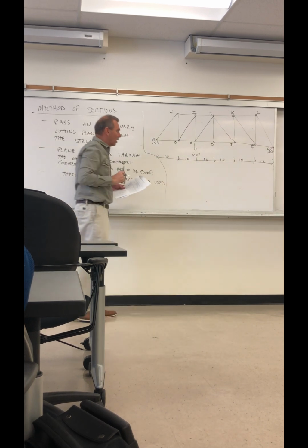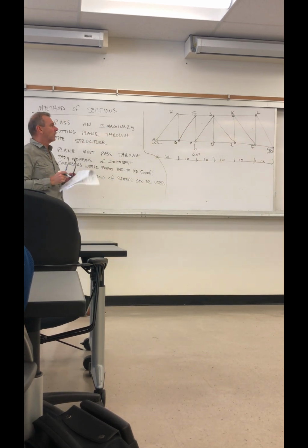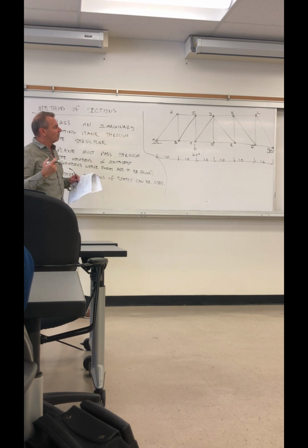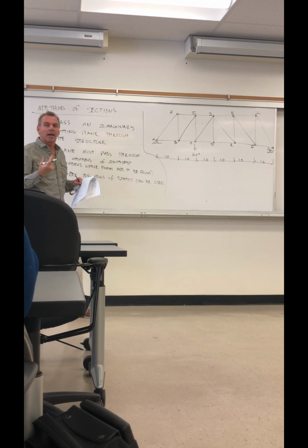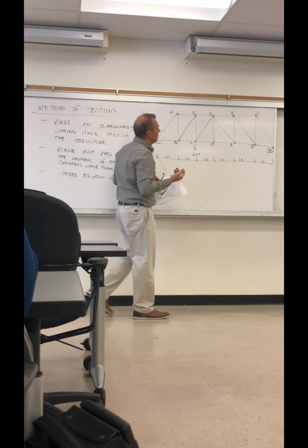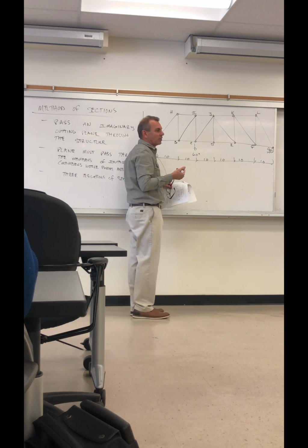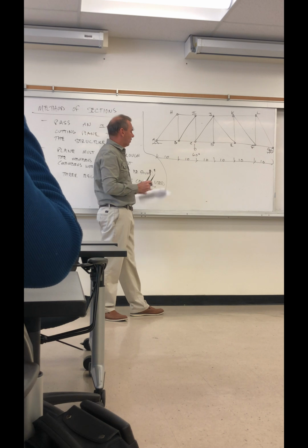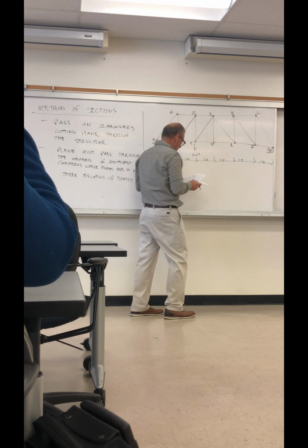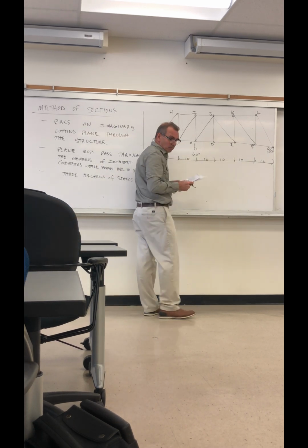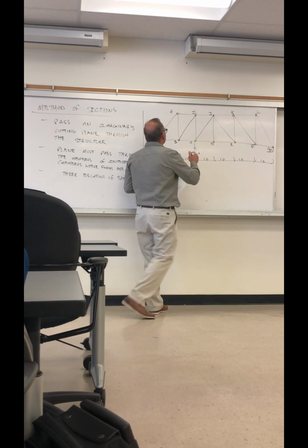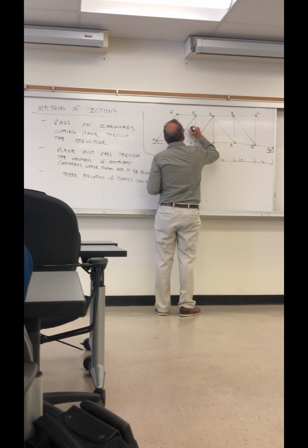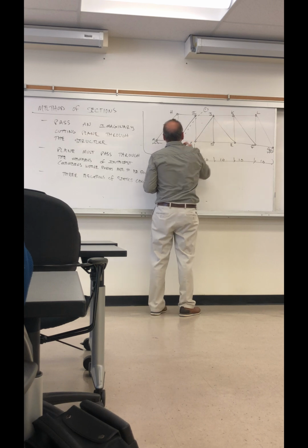What we're going to do is take 4 section cuts, but just be aware, while I'm doing this to demonstrate how the method works, that you are the ones who are going to have to decide where the section cuts are taken. So section 1-1 will be just to the right, a differential distance, of B and I. So right here. See that? 1-1.